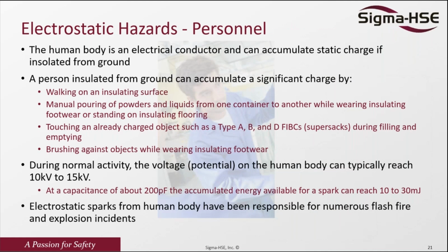The next aspect here is personnel. And sometimes when I say this, people say, oh, really? Can I actually serve as a source of ignition and cause fire? Yes, because the human body is a conductor. And we can actually accumulate static discharge if we are isolated from the ground. So normally when I go to every facility, my shoe is always static dissipative. And a person insulated from the ground can actually accumulate a significant charge by walking on insulating surfaces or manually pouring powder or liquid into maybe a container.